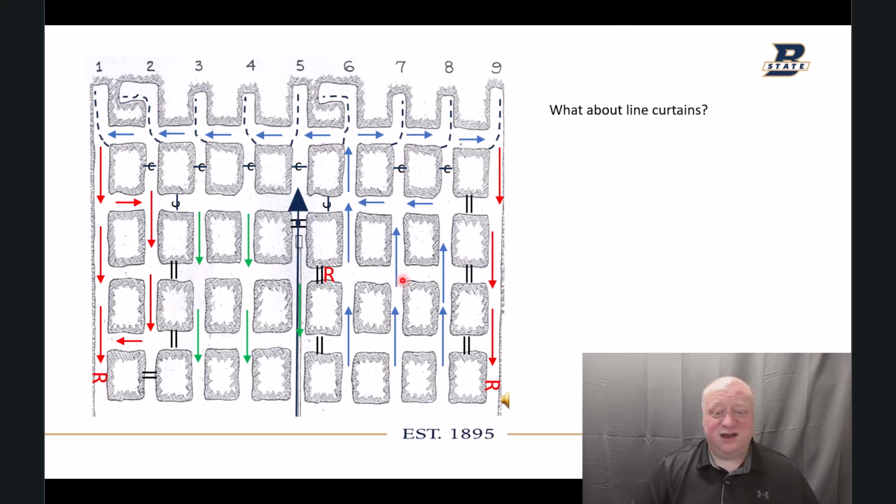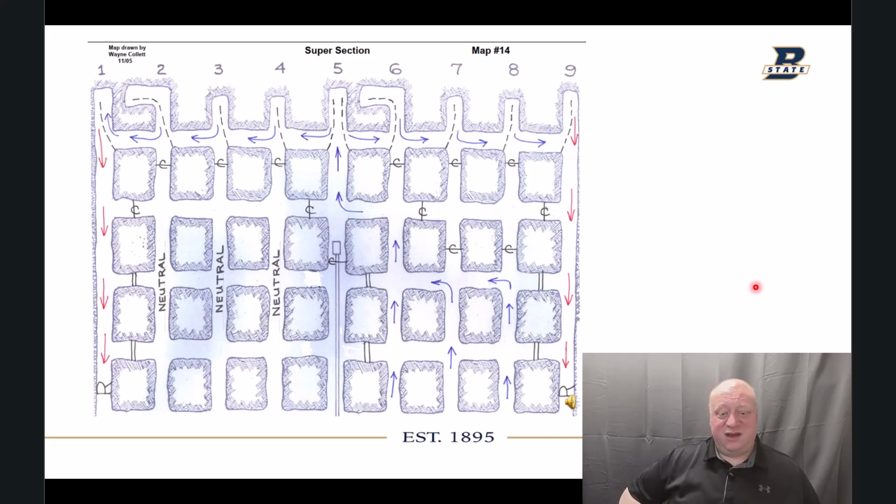We've got intake coming up through these 3 entries. It then comes through this one, splits to both sides. Curtains are on the return side so that the air comes up across the miner and exhausts out the back of the curtain. Returns on both sides. Regulators where they need to be. And that ends up being close to what was drawn by the Kentucky folks.